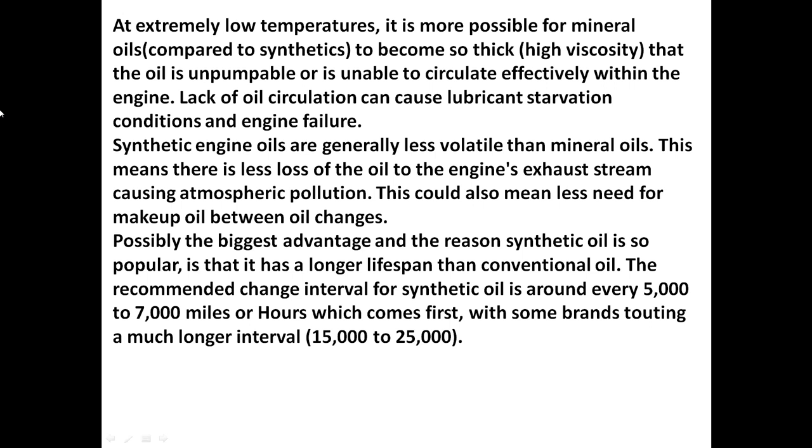At extremely low temperatures, it is more possible for mineral oils to become so thick, with such high viscosity, that the oil is unpumpable, or is unable to circulate effectively within the engine. The lack of oil circulation can cause lubricant starvation conditions and engine failure.